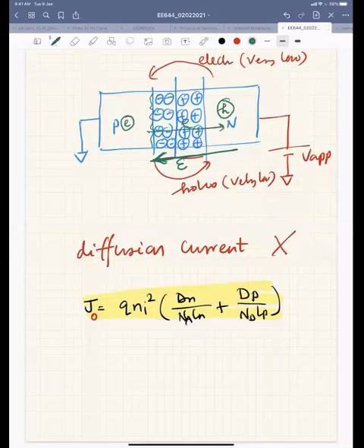Electrons are randomly moving inside the P region, and if by moving they come near the depletion region, they experience this field and are just pulled. So basically, the reverse bias current is because of the minority carriers, and the current is because of drift, because these minority carriers are pulled across, electrons going from P to N side and holes going from N to P.